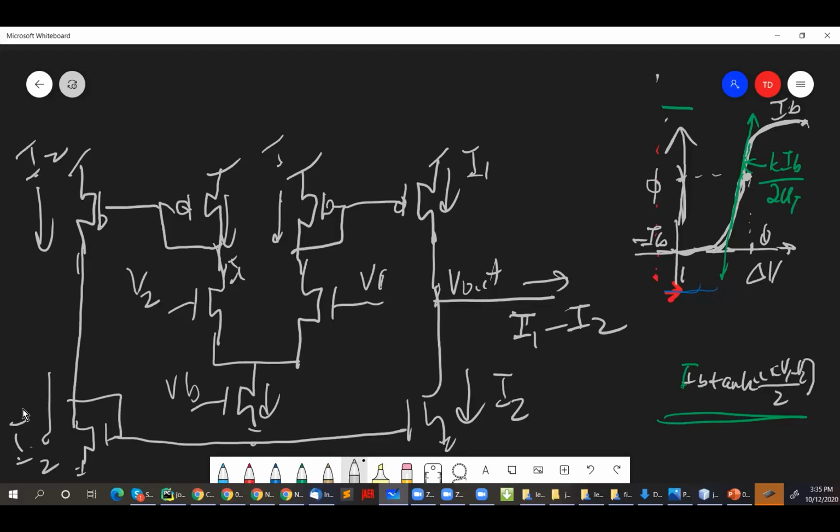And so now you see this output voltage here is not dependent on anything below it. It's just a PFET and an NFET, which means that this output voltage can now swing almost over the whole power supply range. Again, you're going to have some constraint on how far up Vout can reach towards VDD, and you get the same thing on the other side. You'll reach almost close to ground, and it's not going to have this Vmin problem. And this is what we call the wide range transconductance amplifier.